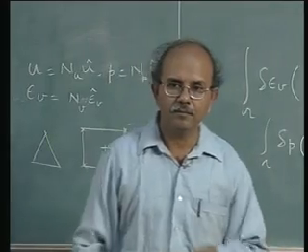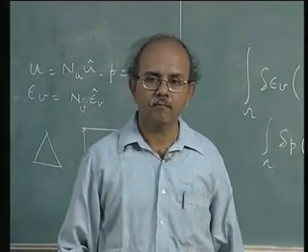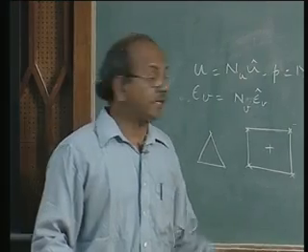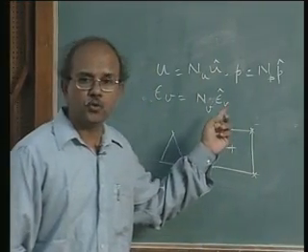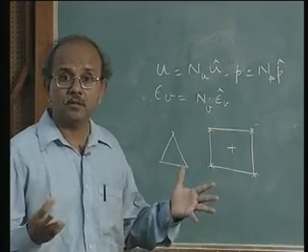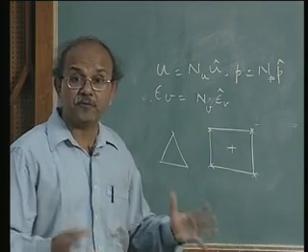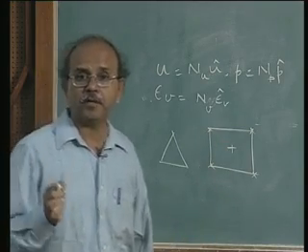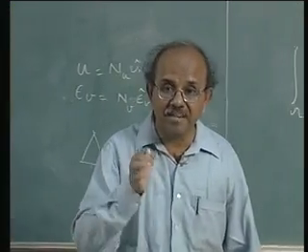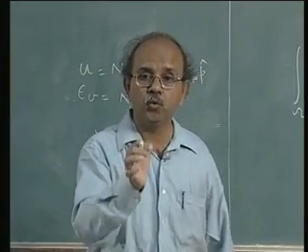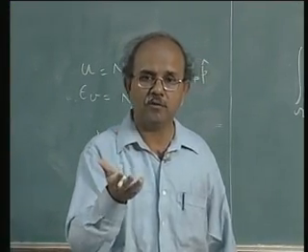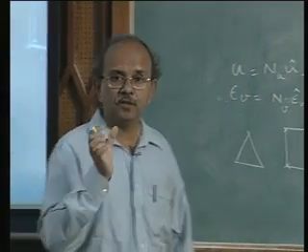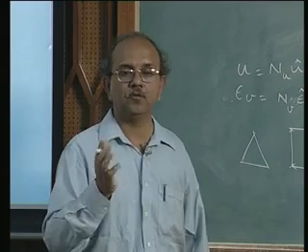In case we have 5 nodes, we'll have 5 Nu's, and the same for the 5 Np's. The N's depend, of course, on the number of degrees of freedom. The question I'm repeating is whether I have the same degrees of freedom for u, p, and epsilon v. I can have p to be constant in one element. In other words, N can be 1.